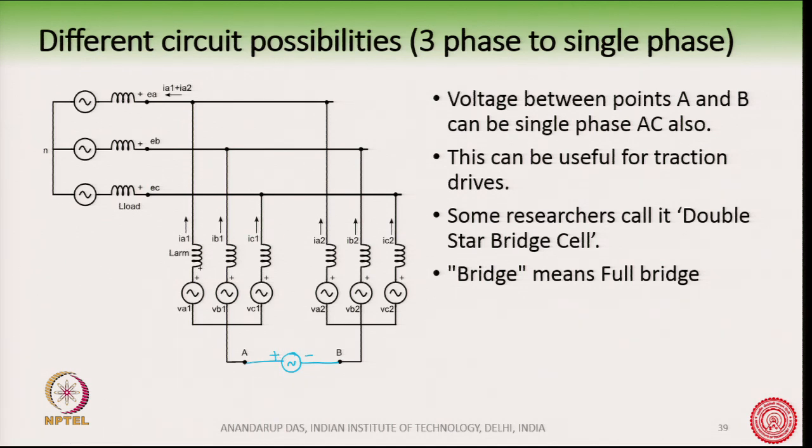So, what we understand is that for the blue colored waveform which we had drawn, if the voltage starts to vary there, then we will be using full bridge cells here and here, so that the instantaneous voltage difference between this voltage source and this voltage source can be supported by the arm voltages here and here. So, we are basically applying Kirchhoff's voltage law, neglecting the inductor drop. You can find out yourself the expression of the voltages of the upper arm and the lower arm when this side is a single phase AC and this side is a 3 phase AC.